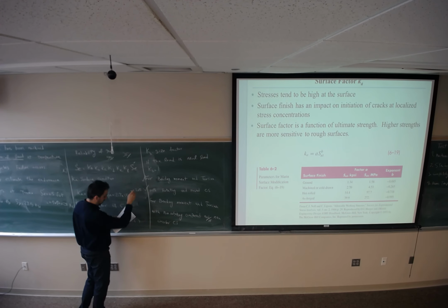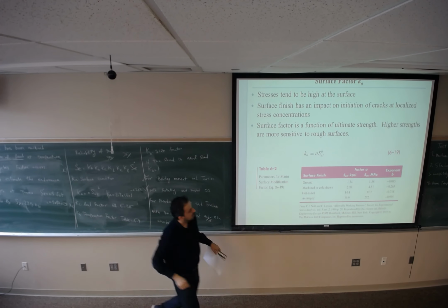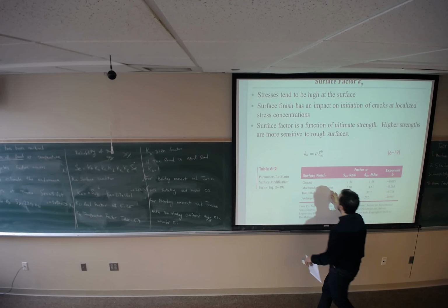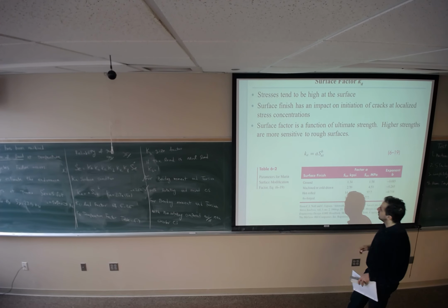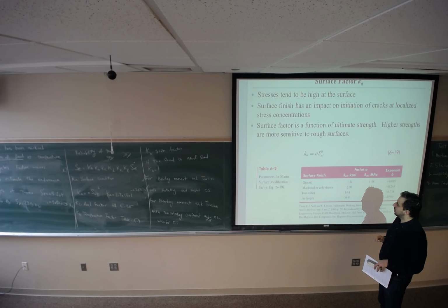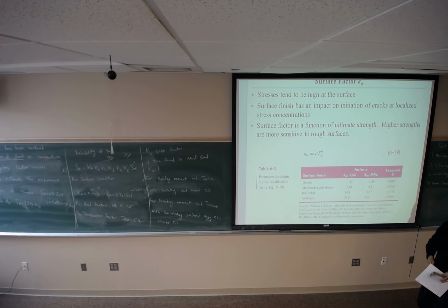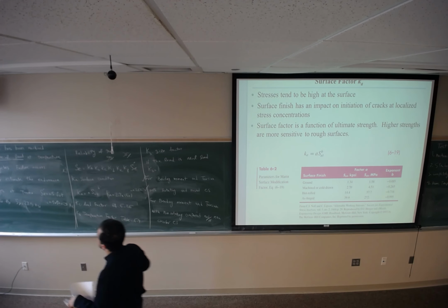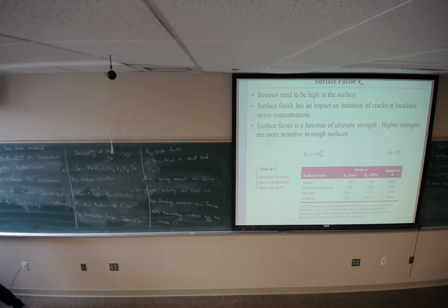0.265. So it says it's machined, but it also says hot roll, like in the machined or cold drawn statements. But we're not cold drawn. It's hot roll material that has then been machined. You get your strength from the fact that it's 1015 hot roll, because hot roll has a different strength. But then afterwards it says it has been machined. So that material has been hot rolled, but then you have a surface finish, so it's the machining surface finish.